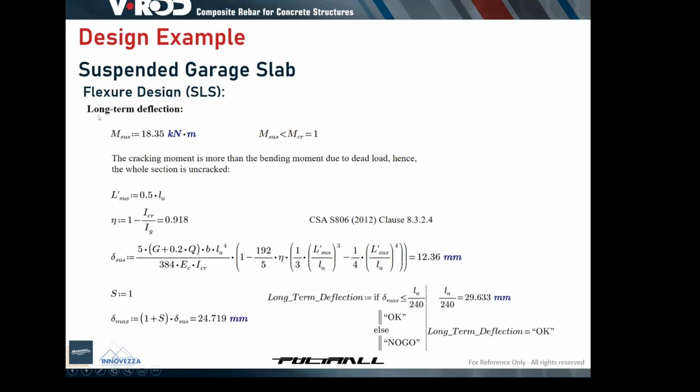Then we calculated the long-term deflection per the sustained load, and here the sustained load is assumed to be the dead load plus 20% of the live load. So we calculated the long-term deflection, which was about 25 millimeter. This is again less than the requirement of 29.6 millimeter.